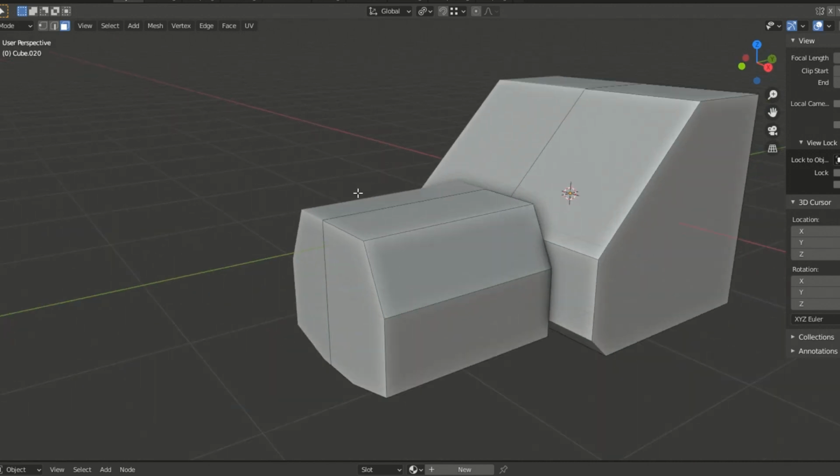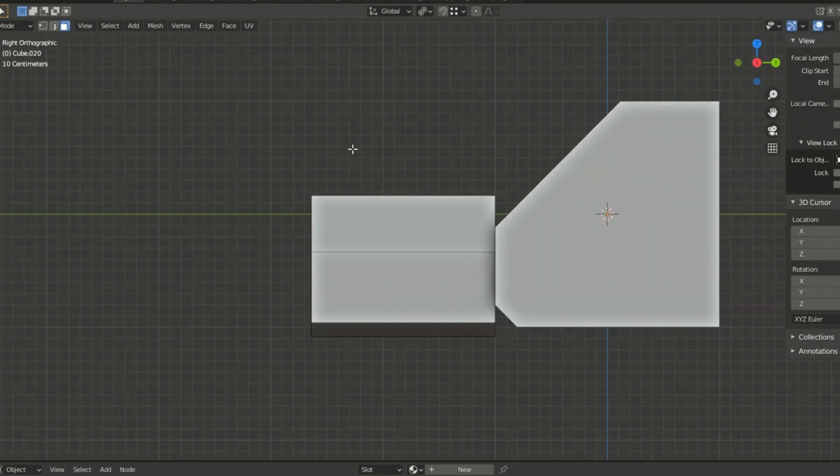In fact, for Grid Modeler, there is a special function. If I do not select anything and then I run Grid Modeler, it will use my current view pane to execute Grid Modeler. So I will show you how to do it. First, I do not select anything. Then I switch to numpad 3, the left view mode.